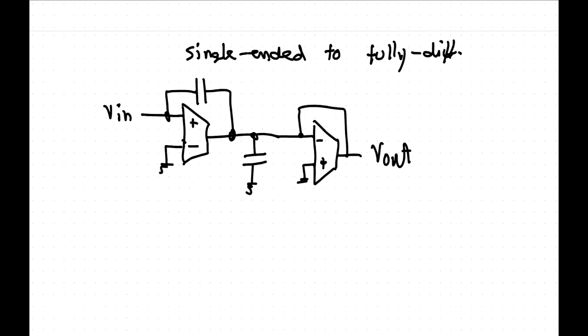We're just putting more output. It's not a drama. But if you can arrange your filter such that for all your transconductors you have one grounded potential, then you can mirror the circuit in ground and swap all the plus and minuses on the transconductor.